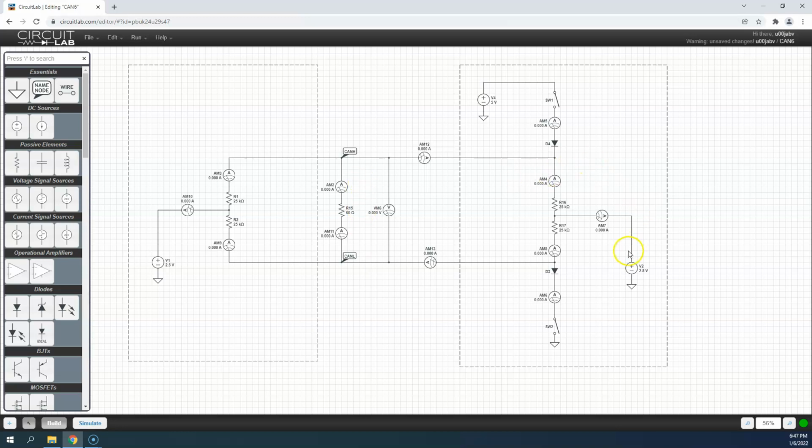So you saw that there. This is how it works in perfect theory, if there's absolutely no path to ground anywhere, and everything is the exact value it's supposed to be, unlike real stuff, which varies. This isn't going to be exactly 2.5 volts. It would be 2.49999 or something. So yes, there would be some current flow from this one over to this one, but because they're exactly 2.5 volts, everything here has a potential of 2.5 volts, so there's no current flow.